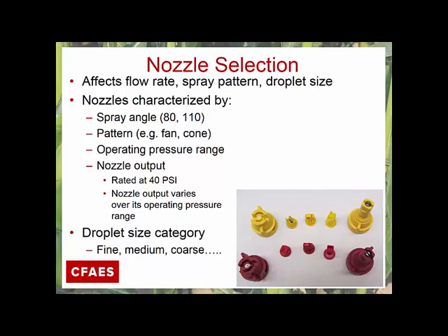All nozzles are going to have an operating pressure range, and it's very important that you don't use the nozzles outside of their operating pressure ranges. All nozzle outputs are rated at 40 psi, but of course their output or their flow is going to depend upon your actual operating pressure.